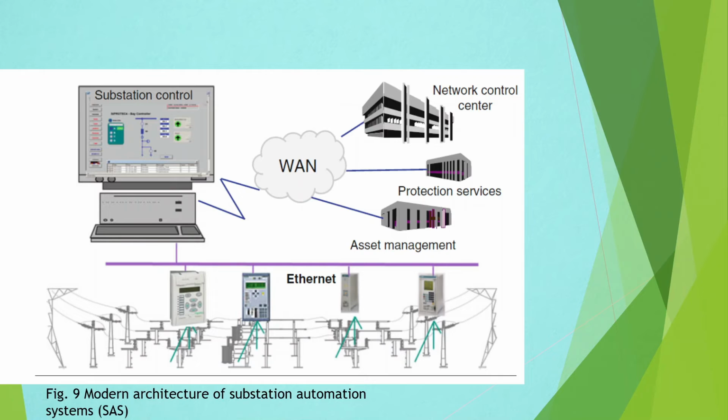The screen of the industrial computer displays the overall substation scheme and offers the selection of a large amount of detailed schemes, various event logs, diagrams, measurements and fault recorders. Video observation and others. The flag relays for the recognition of the events are no longer applied. The monitoring comfort is fundamentally improved.